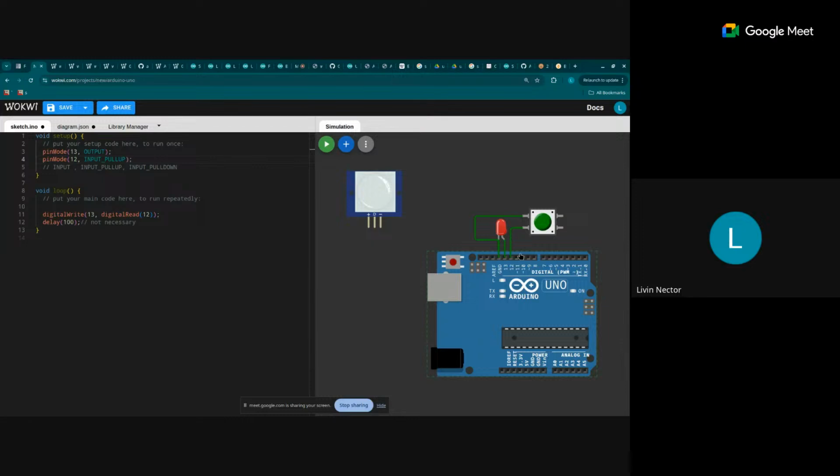But if you want to make it predictable, you want to set the voltage to a particular value. And one more thing, if you put it to input mode instead of pull up, the voltage there would be floating, which means it won't be high, so it may have different behavior than you expect. You set the mode to input when we are using an active device like this.